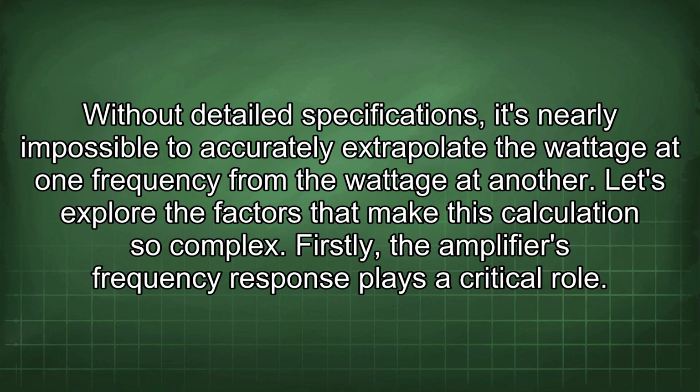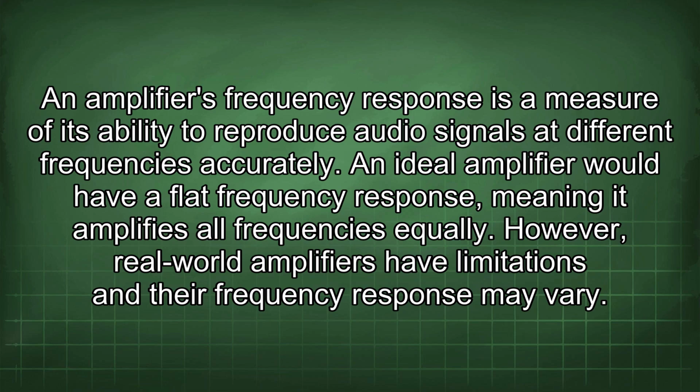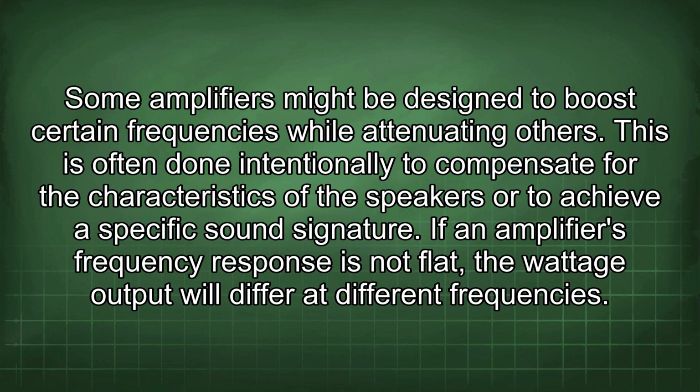Firstly, the amplifier's frequency response plays a critical role. An amplifier's frequency response is a measure of its ability to reproduce audio signals at different frequencies accurately. An ideal amplifier would have a flat frequency response, meaning it amplifies all frequencies equally. However, real-world amplifiers have limitations and their frequency response may vary. Some amplifiers might be designed to boost certain frequencies while attenuating others. This is often done intentionally to compensate for the characteristics of the speakers or to achieve a specific sound signature.